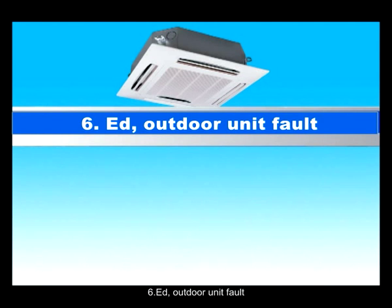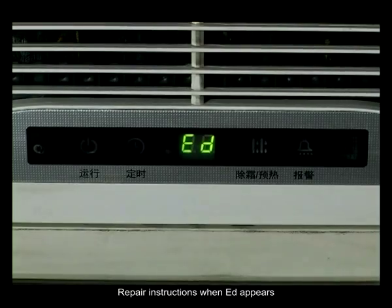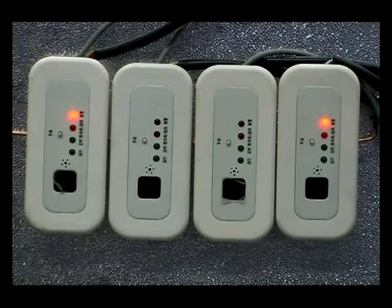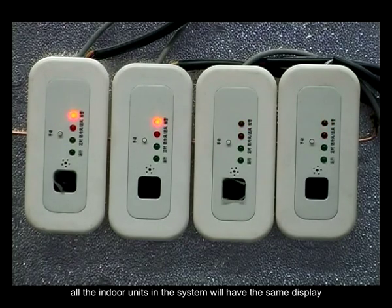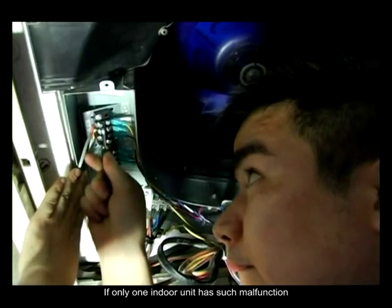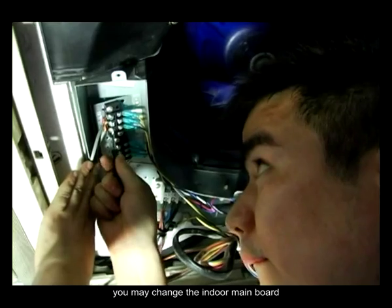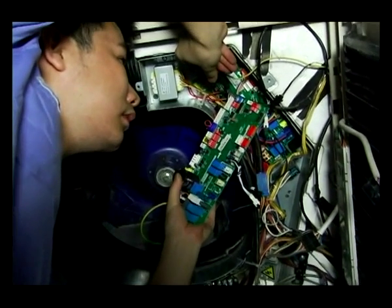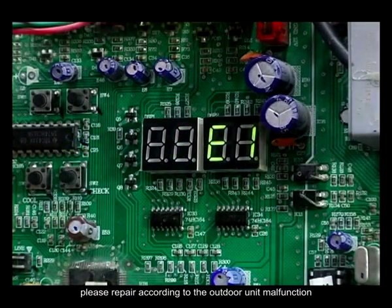6. ED outdoor unit fault. Repair instructions when ED appears. When indoor units display outdoor unit has malfunction, all the indoor units in the system will have the same display. If one indoor unit has such malfunction, after confirming the wiring is reliable, you may change the indoor main board. If malfunction happens to all the indoor units in the same system, please repair according to the outdoor unit malfunction.